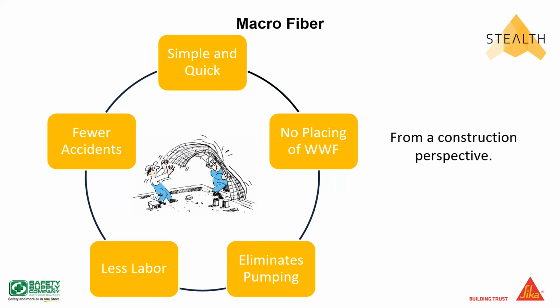So what that means is maybe you had a number 3 rebar on 12-inch centers chaired 2 inches from the bottom of the slab. Well, you can't drive on that, so you'd have to pump it. In this case, like I said, the strength is in the truck, in the concrete truck. So it eliminates pumping. Less labor, much less labor. When you talk about replacing welded wire fabric, especially rebar, you don't have to handle the rebar. You don't have to tie the rebar. You don't have to chair the rebar. Much less labor involved.